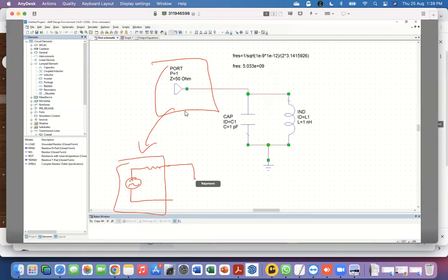and now this is driving my LC circuit, we know that at resonance, there is going to be some energy in the inductor and in the capacitor. There is going to be some voltage and current which is flowing through. So how is it that if this cannot absorb any energy, then how is there energy in this circuit in the first place? Because remember, if you think from time t equal to 0, when you maybe turned on the signal, initially there was nothing, there were no currents or voltages here, but all the signals were reflected and yet no energy is here. It seems to be inconsistent with this idea, okay?